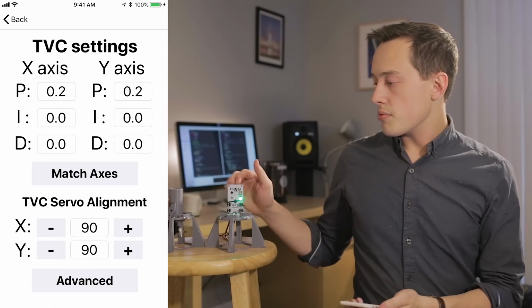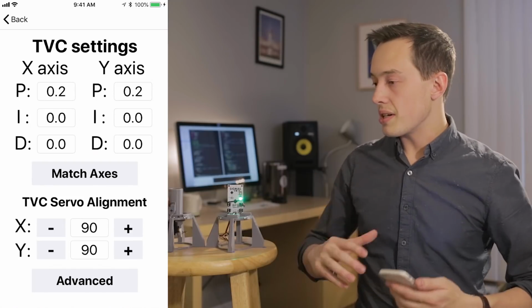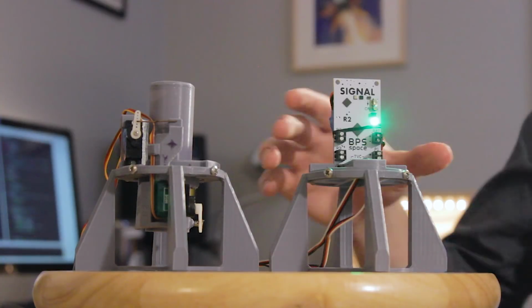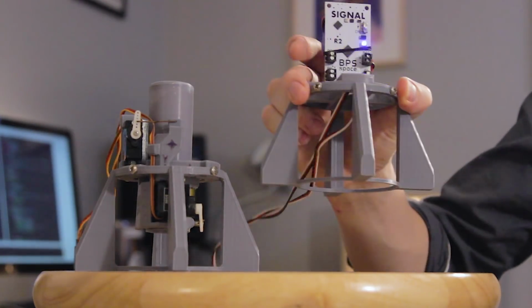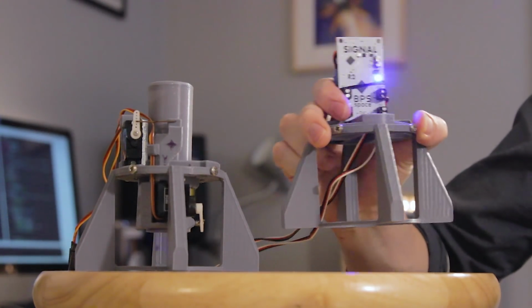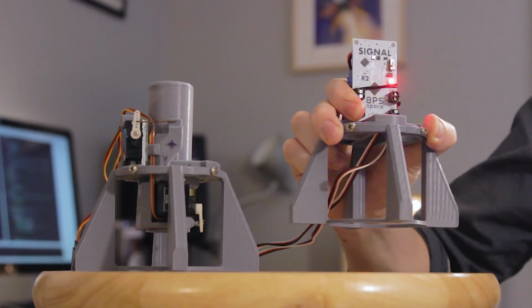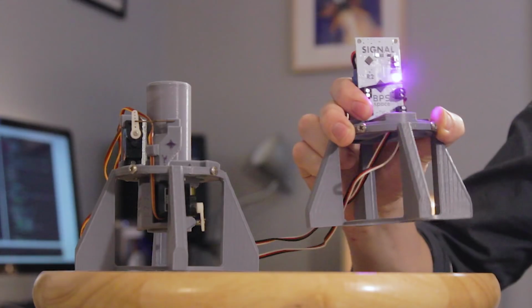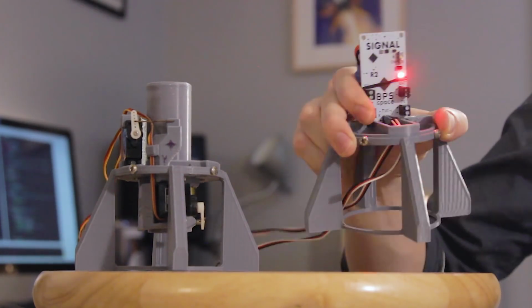that are actually showing what's going on with the computer. We can confirm this. We just changed our control to entirely proportional, so there's no derivative. That's the D in the PID. If I launch the rocket here, you can see it's totally proportional. Even if I go fast, there's no sort of advanced correction happening with that derivative value.